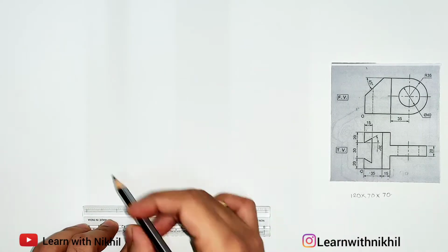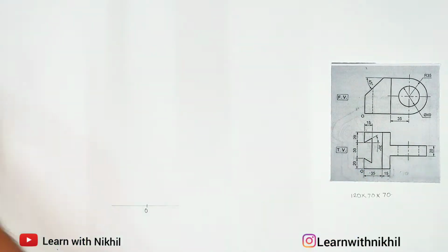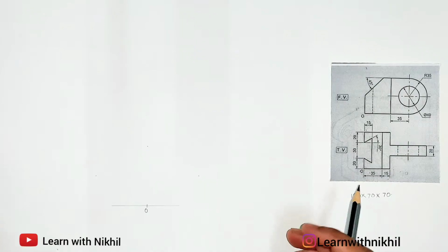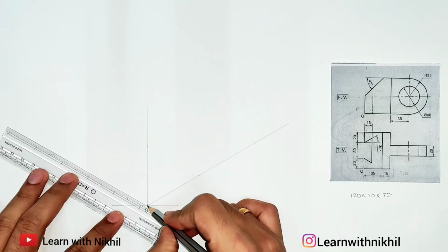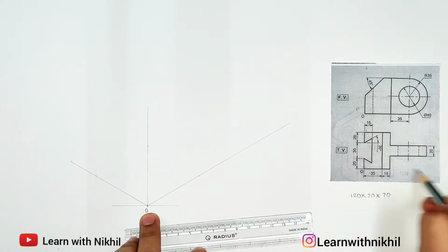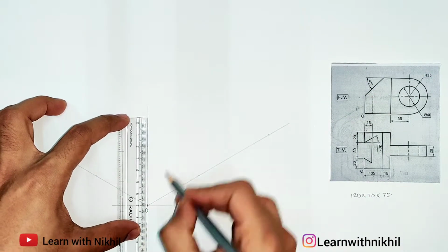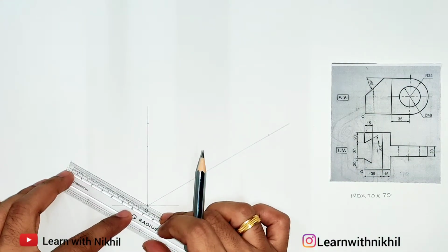First we will draw a straight horizontal line. We'll mark the point O. Then from the O on the right side, as you can see, we have to draw its front view. Now we will draw the angles, that is 90 degree, 90 degree, 30 degree, drawing light lines through them. Now here we have a total length of 120. As this is point O, on the right side we have 120 millimeter. So that's why we had left maximum space on the right side. Height is 70 millimeter, this height is 70 millimeter, and the depth again is 70 millimeter.